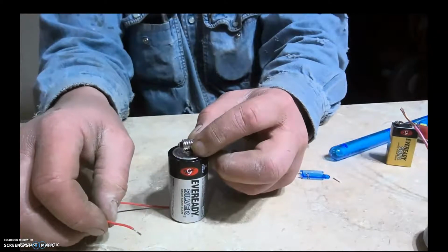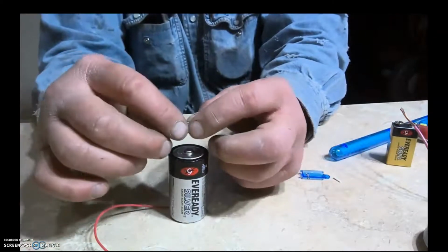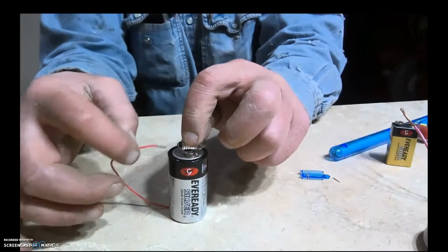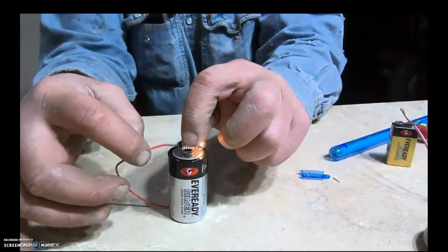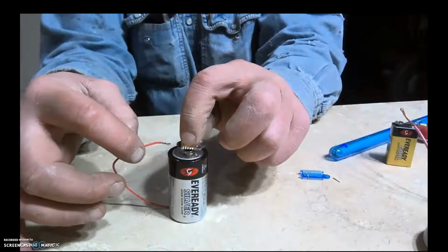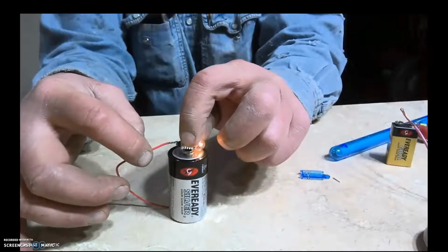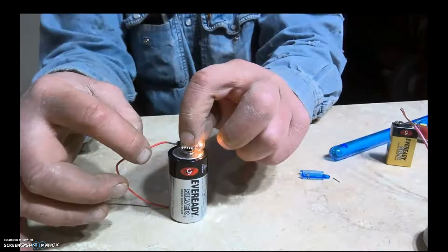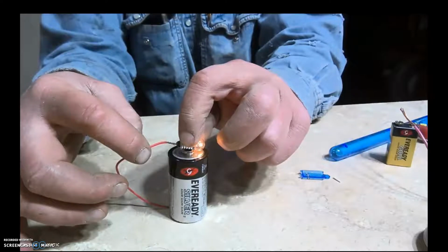So now turn the bulb and place the side of the screw cap on the positive terminal. So what do you think the other end of the wire needs to touch to make the bulb light? We turned it on its side. The positive point to the battery of the bulb. Okay, so once again, how are the electrons moving in this closed circuit? From the negative terminal of the battery through the wire into the tip of the bulb, through one of the lead wires, through the filament, down the other lead wire, through the side of the screw cap, and into the positive terminal of the battery.